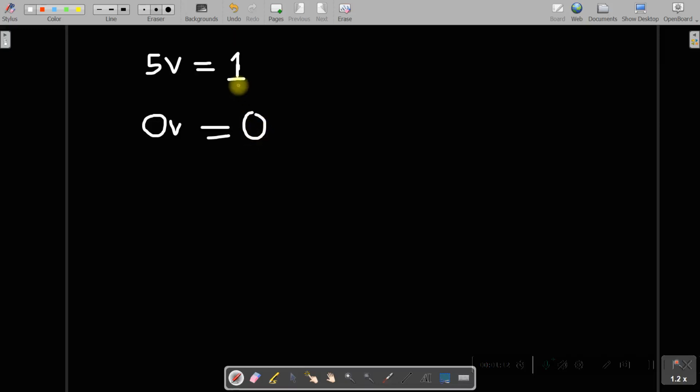So how do we do that? Because we know that everything is represented in zeros and ones in your computer. Now, for electronics like your computer and some other devices, they usually use 5 volts to represent 1 and 0 volts to represent 0. Some embedded devices would also use 3.3 volts to represent a high, and 0 volts is always going to be 0 or low. So that's basically what a digital signal is.